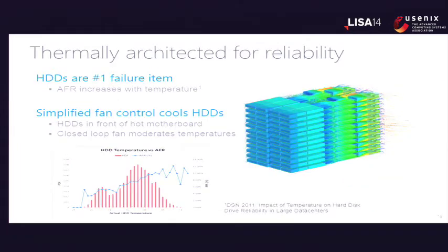Talking about reliability, hard drives are usually the ones that fail most often. The manufacturers will say that hard drive failure rates are 3%. In reality, they tend to be more like 6%. So then you start looking at how do I make sure that the mechanics of the hard drive are what they are? It's amazing that they even work, actually, if you think about it. The heads of the drives are over the platter by, it's like 2 nanometers or something. I'm just amazed that we have gotten this far and continue to increase the areal density. But in any case, they do fail.